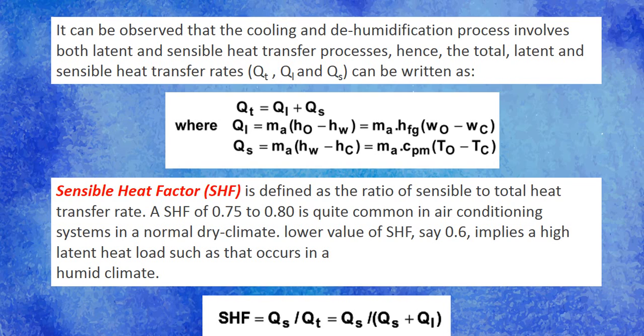Where are you going to get this? You can get this from the psychrometric chart, or this can be read from the steam tables. You just base it on the saturated liquid enthalpy based on the temperature. Now, for the m Cp delta T formula, of course that will use the final temperature minus the initial temperature. So this would be how you're going to determine the latent heat transferred and the sensible heat transferred, the amount of heat that is.